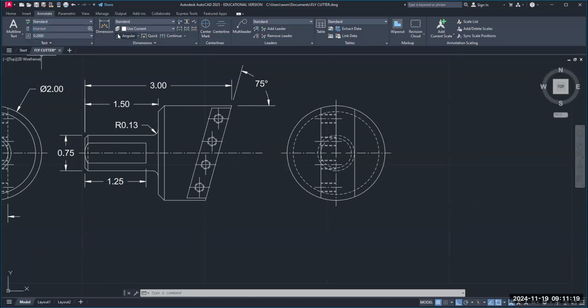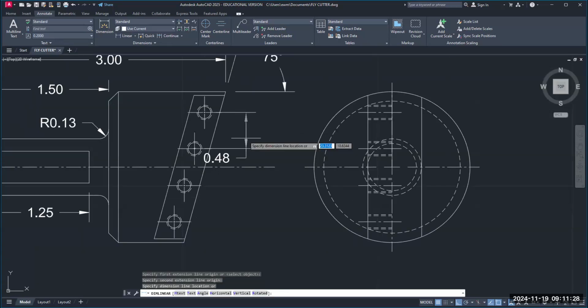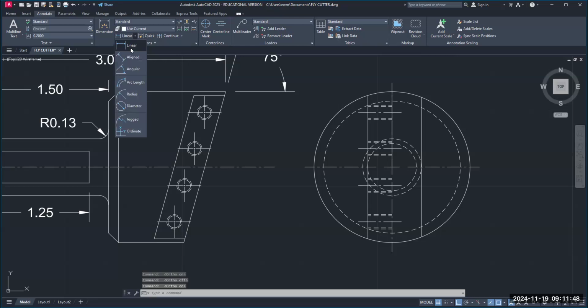Okay. I'm going to do linear here, here. All right, let's see how this is a problem, right? Now, if I hit F8, well, no, don't, here, hit escape, I'm sorry. Make sure ortho is on. You can see down the bottom, you hit F8, ortho off, ortho on. So I'm going to click here. And this time I'm going to select. Now I like my gap there. Click.